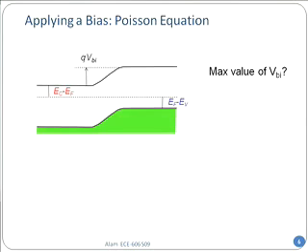So what is V_bi then? Do you realize that it is essentially equal to the band gap? So when you have a new semiconductor and you just want to quickly solve a problem and you don't have the effective density of states and everything, you can quickly get qV_bi simply by equating it to the band gap.